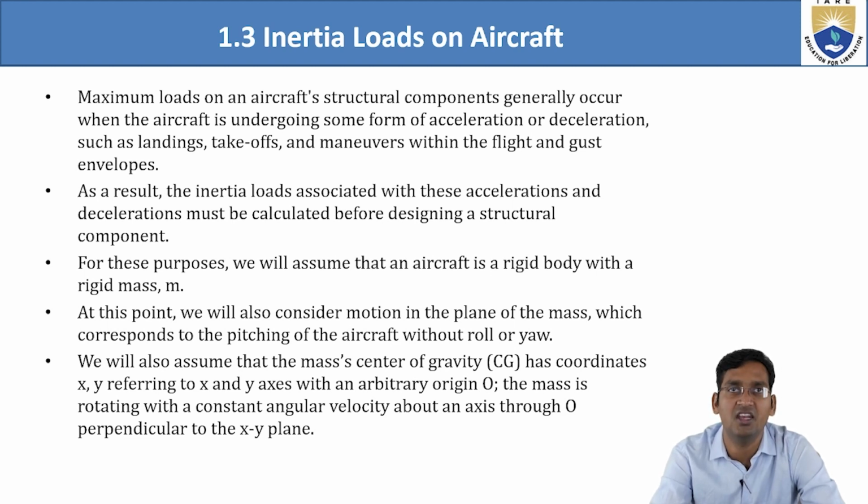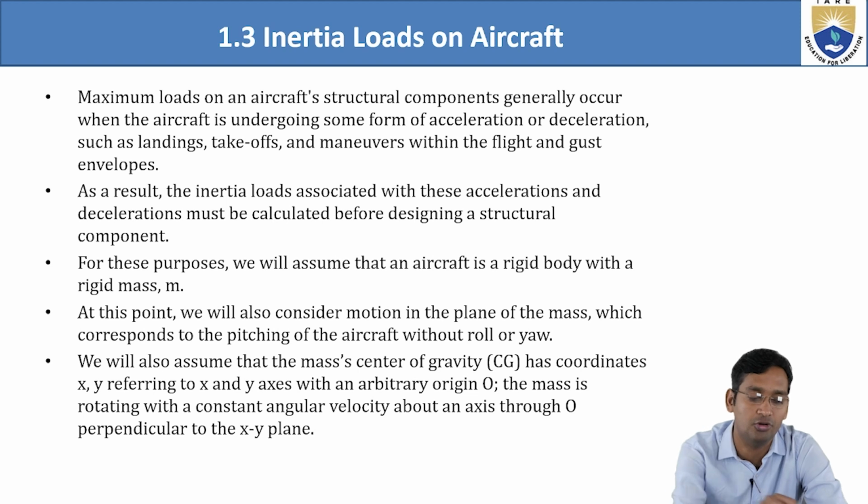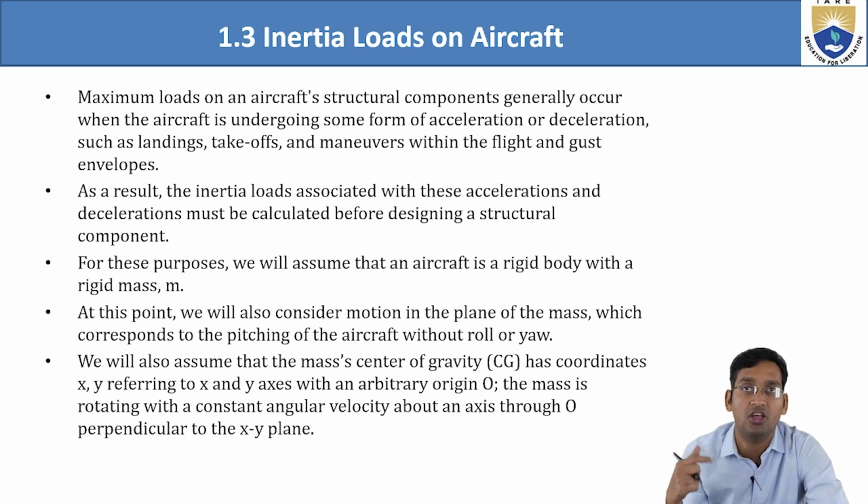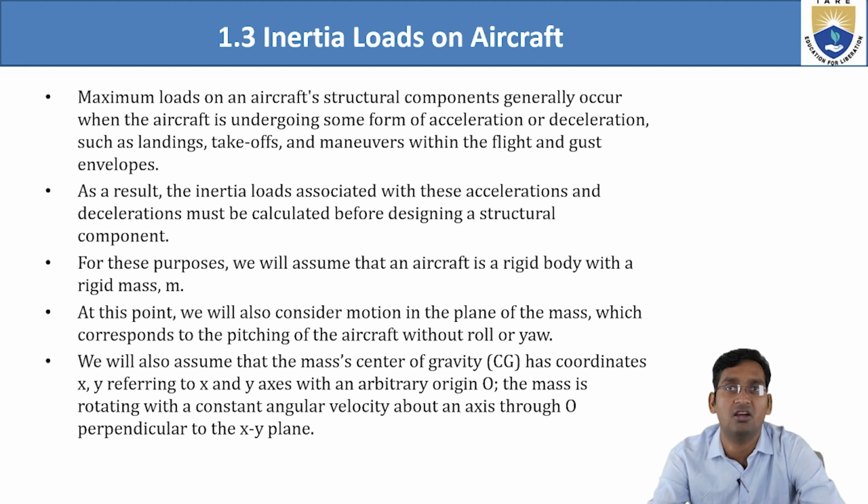As a result, the inertia load associated with these accelerations and decelerations must be calculated before designing a structural component. So before designing a component, how much strain there should be, how much inertia load will act, and how much acceleration and deceleration we can allow, we have to calculate first. For this purpose, we will assume that an aircraft is a rigid body with a rigid mass m. So for that mass only, we need to find it.